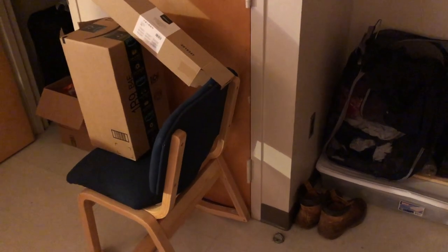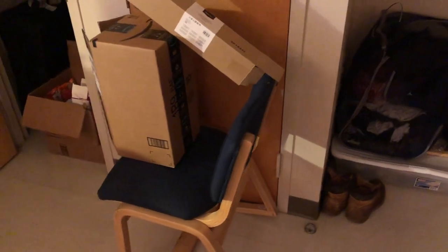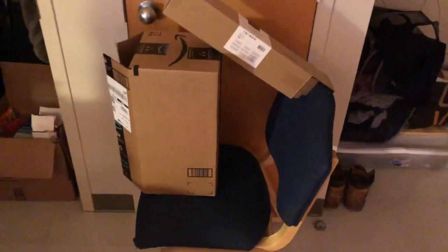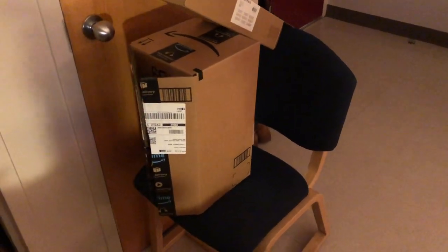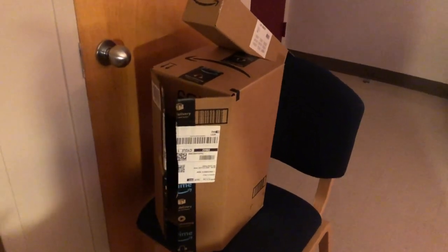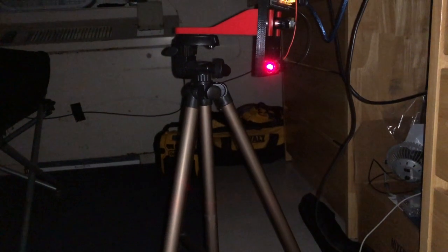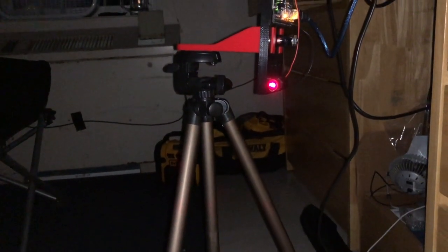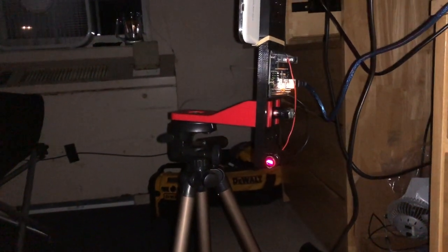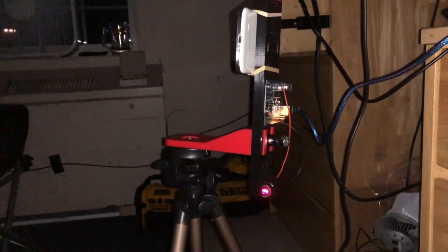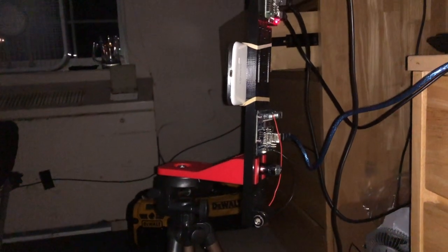The first test with our LiDAR sensor was to scan something in our apartment, so I chose a couple of Amazon boxes on top of a chair so it would be distinguishable. Step 1 of using our LiDAR sensor is to shine the red line laser onto our object at different IMU angles. That way the IMU angle captures the Z coordinate, while our computer vision with our camera captures the X and Y coordinates of the red line laser points.